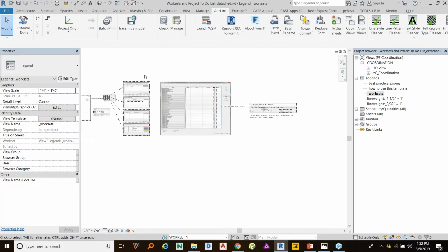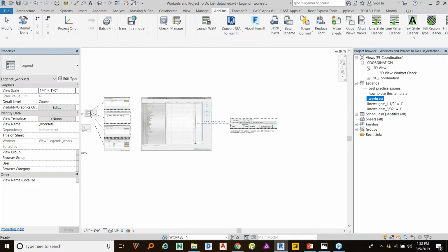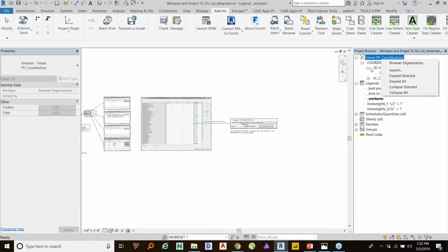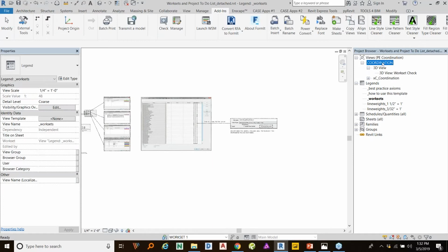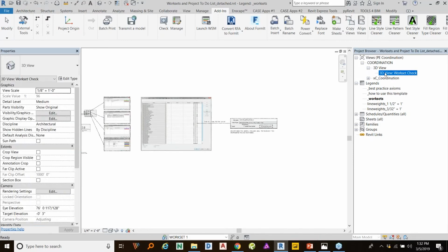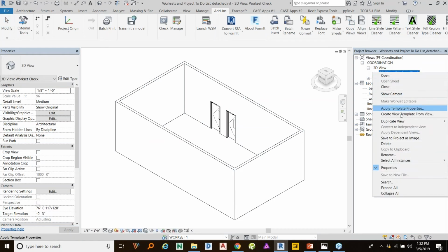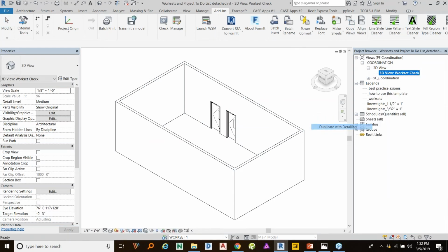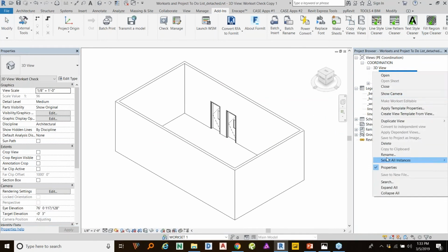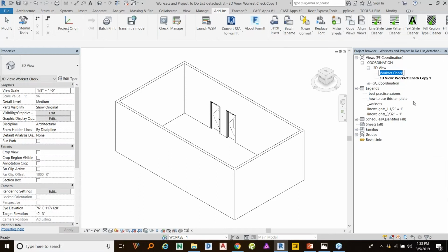And then finally, if you really wanted to, which I highly recommend, and here I'm going to basically take a look at just like a 3D view. You could set up multiple 3D views, right? You basically duplicate them and continue them, and you can say, this is, in my case, I'm just going to say walls, work set, check, and then you can turn things on and off.